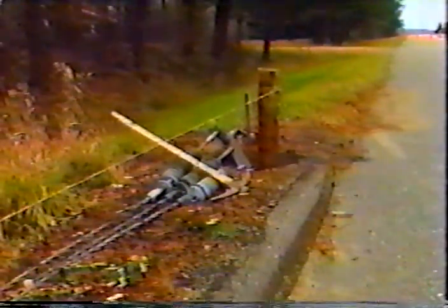Bolts in the plate beam may have been bent, and the holes for the bolts, although still straight, may have been stretched. Both conditions require repair because holes that have stretched will not provide the strength needed for the next hit. All of the anchors have to be checked. Damaged posts and cables have to be replaced. Cable splices have to be checked as well as the turnbuckles. Only when you have checked and repaired each element in that system do you know that the system is adequately prepared for the next motorist.